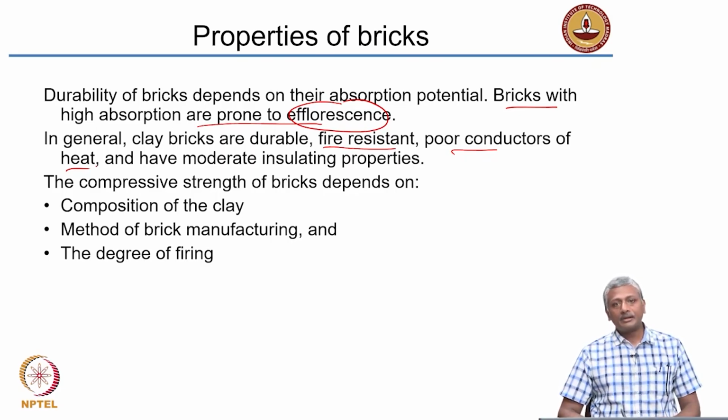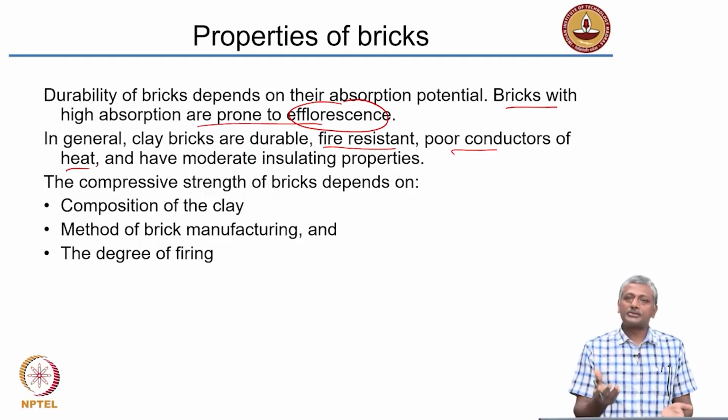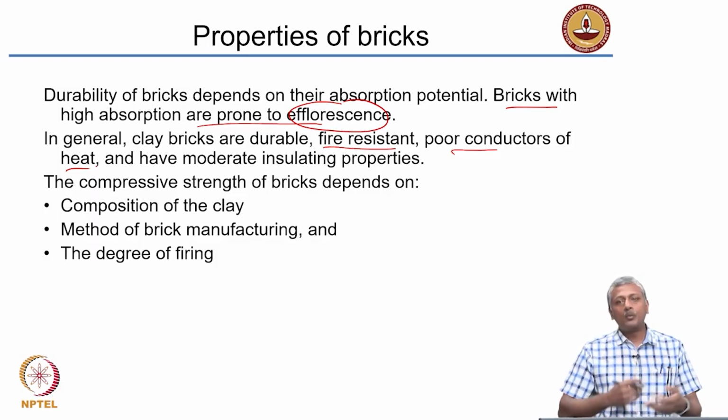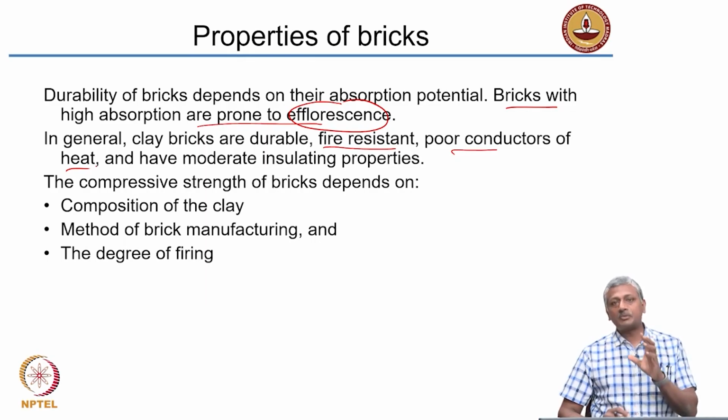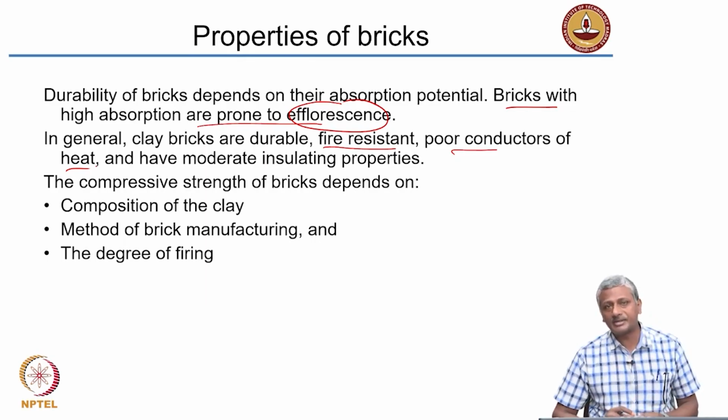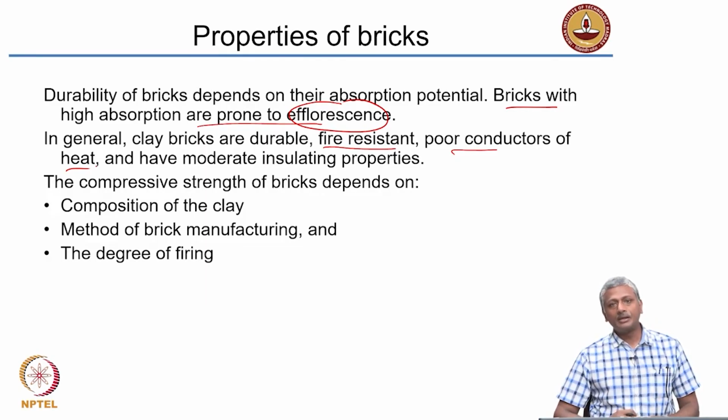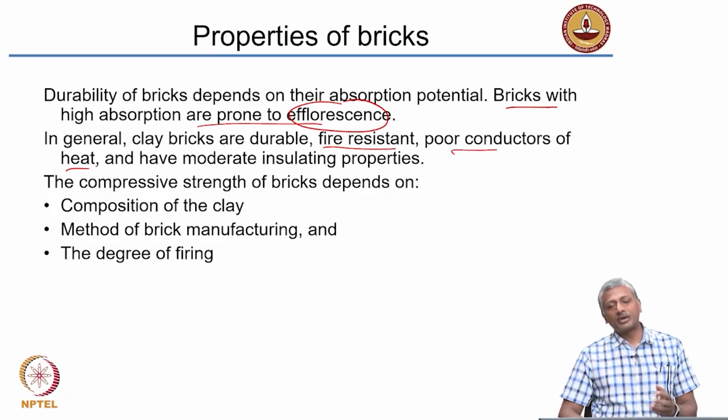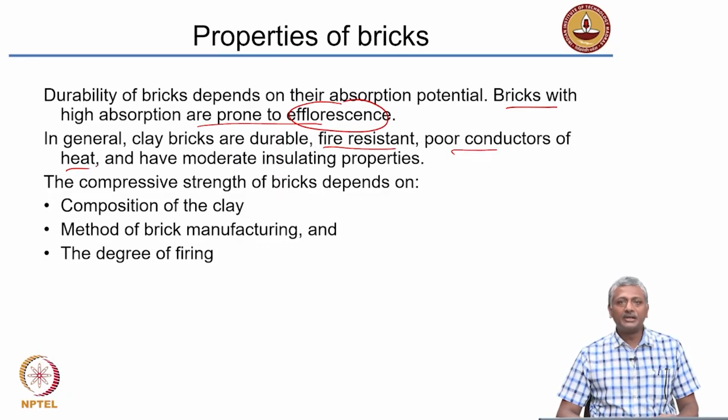Okay, right? Just as I said, for a building brick, strength and water absorption are important. For a flooring brick, abrasion resistance is quite important because you have weights getting carried on the surface. So again, all these aspects need to be thought about before designing the material. Now the issue is with bricks, you have very little choice in terms of engineering the material quality to a large extent, because it all depends on the quality of the soil that you have in a particular location.